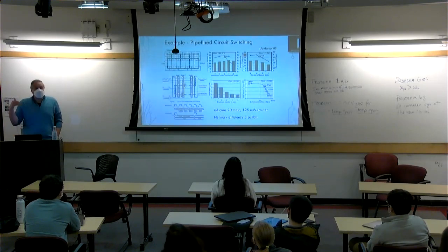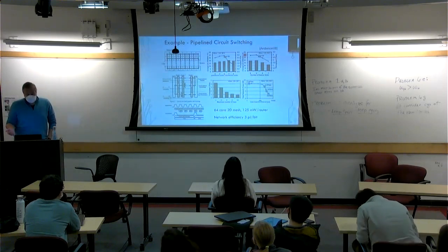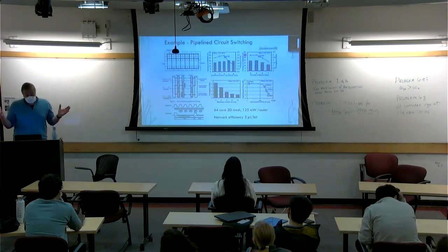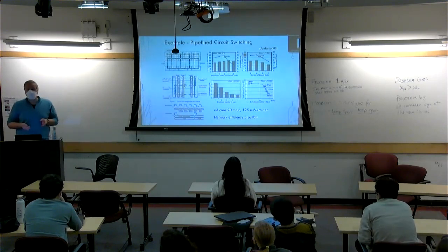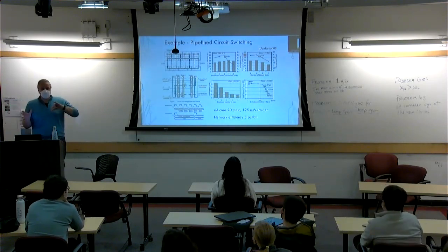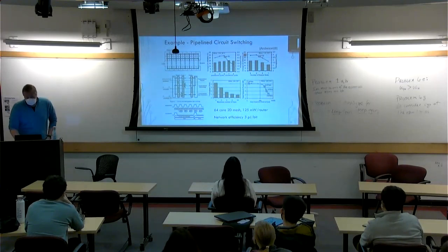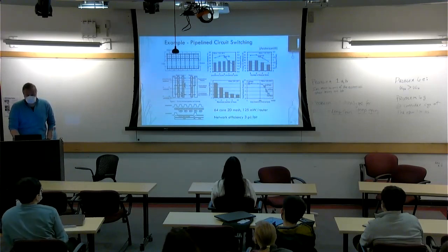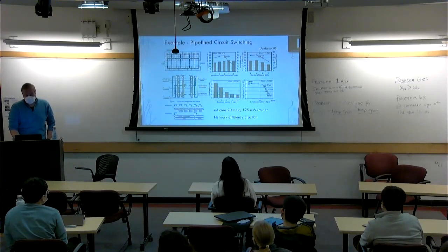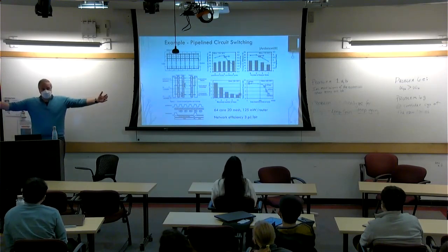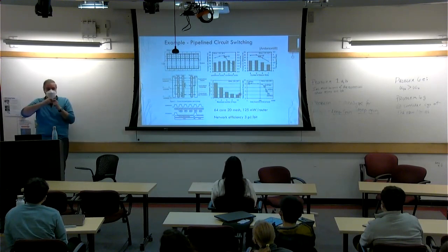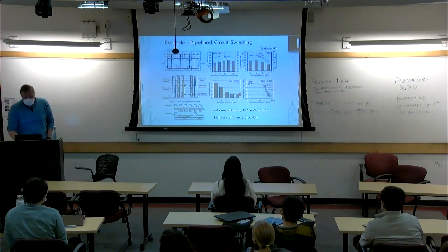So people actually experimented with these ideas. So Anderson from Intel Labs had this, I believe it was 64 core 2D mesh that was like packet circuit reconfigurable. So you can play with different traffic scenarios and understand kind of the trade-offs there. So some interesting things, of course, that you can see logically is that as the number of hops increases, right, your effective throughput goes down because of this overhead of time that it's required to go and set up the channel, right? And certain things like that.